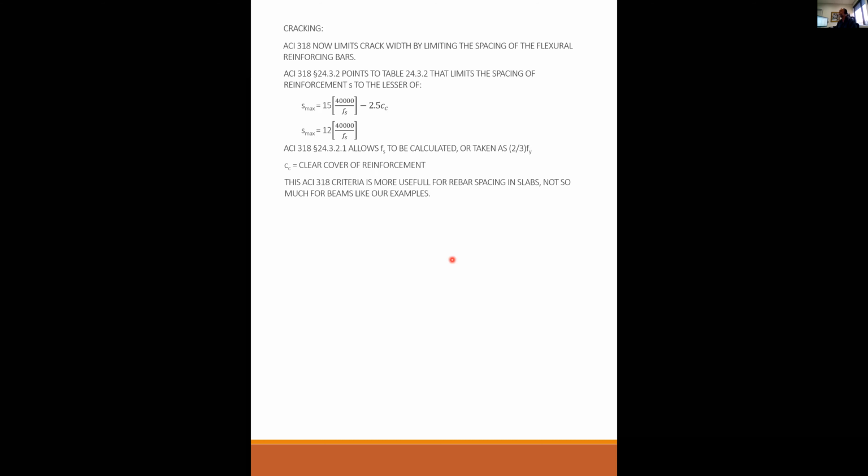That is why after you have chosen the height of the beam, which calculates the D, and chosen the steel, you need to always go back and check your minimum steel, your epsilon sub T greater than 0.005, and is phi Mn greater than Mu. You have to make all those checks because you've made all these choices that may or may not pan out. All right, that was a long speech.